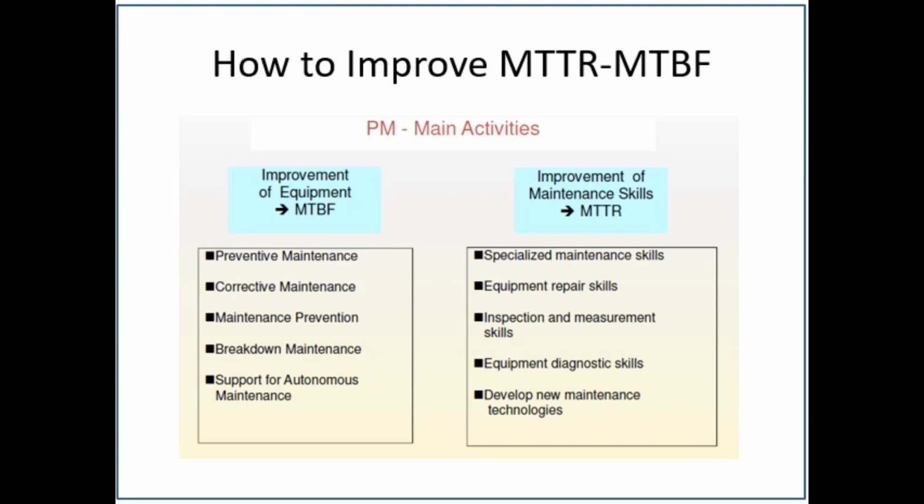How to improve MTTR and MTBF? Whenever we talk about the MTBF, it is the time lapse between two failures. So MTBF has to be backed up with good proactive action, which means good preventive maintenance and good corrective maintenance. Anything that avoids my machine going into breakdown has to be done in order to improve my MTBF. Whereas with MTTR, the machine is already in breakdown and we need to make it live as early as possible.